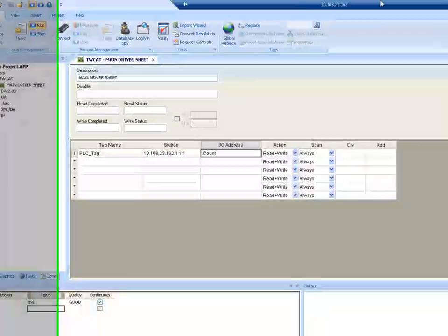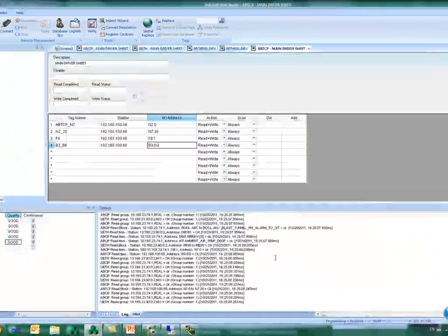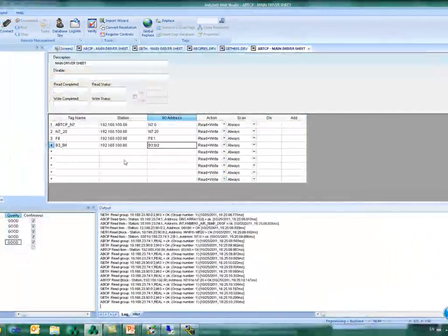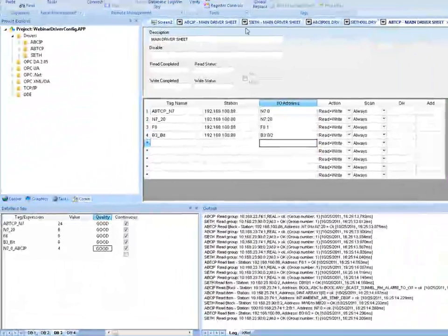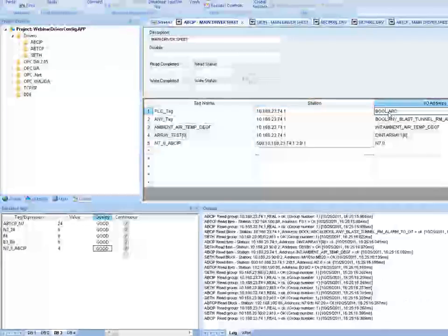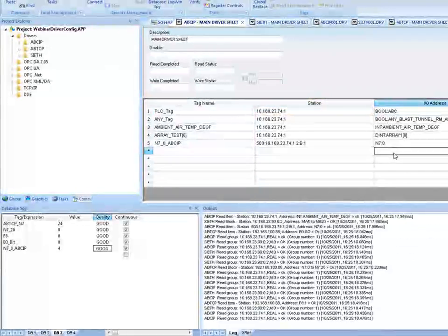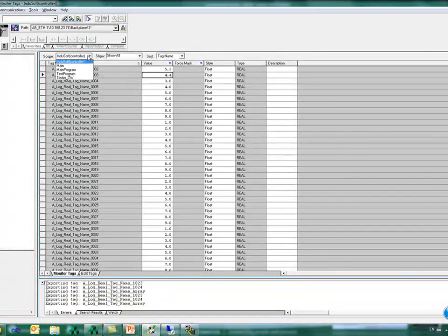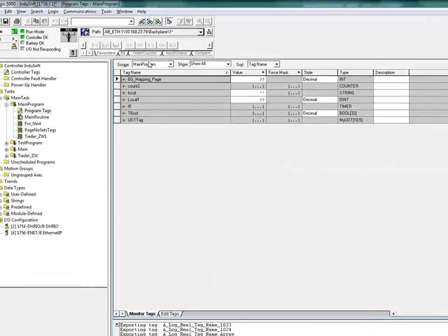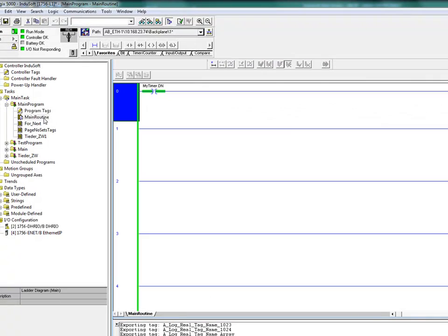All right, so we have seen some Siemens with fixed addresses. We have seen some Allen Bradley where you have tag names. The last curiosity on Allen Bradley, if you have a program tag, for example, you have here a program called main program right here, where we have some tags on this main program that were declared here.